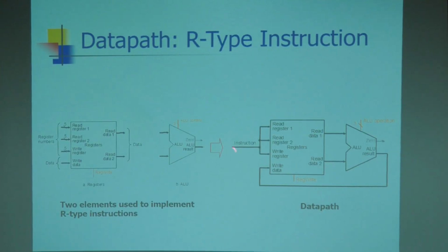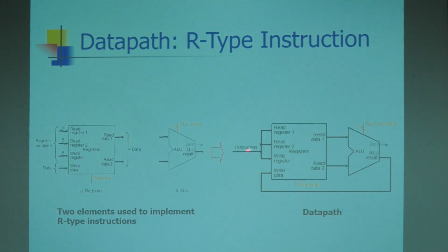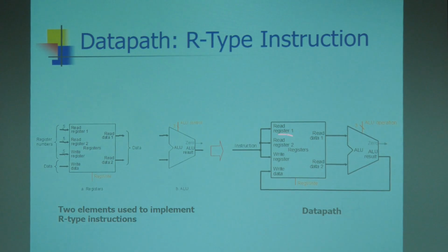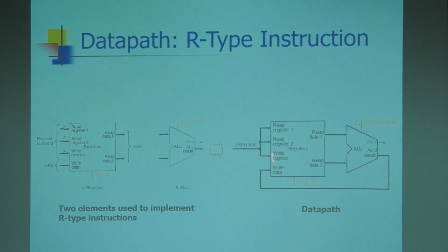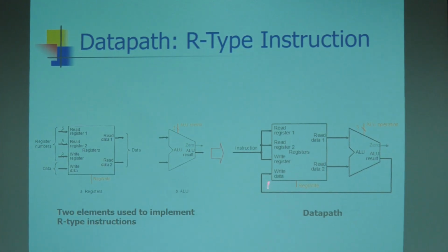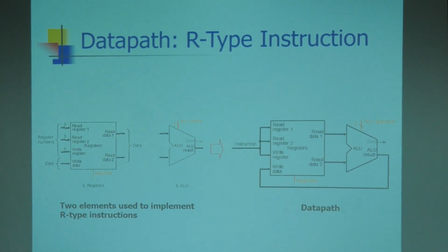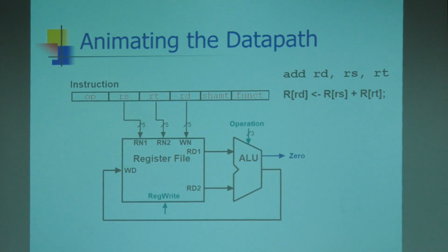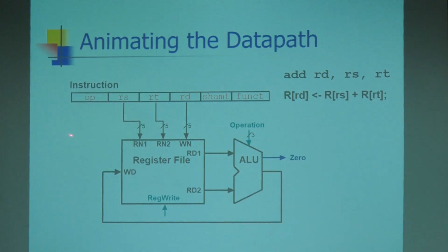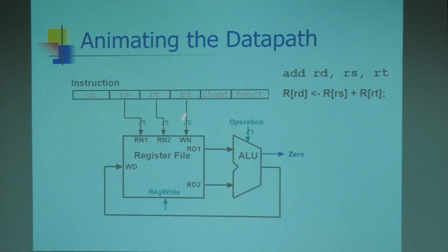So these 15 bits are taken from the instruction template, and it will select 2 read registers. Then the 2 read register contents are going to be added. Then the result is written to the write register. If you see the example, you can understand. These are the 2 read registers RS and RT, 5 bits each, and this one is the destination write register address.